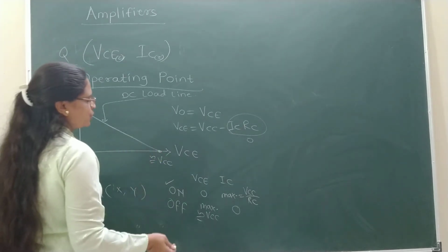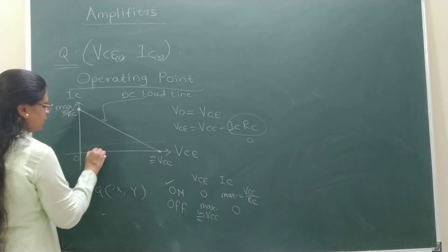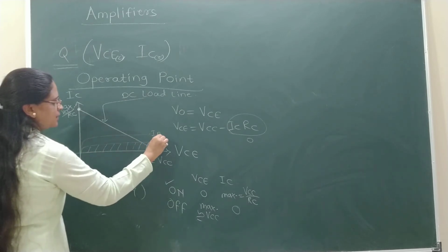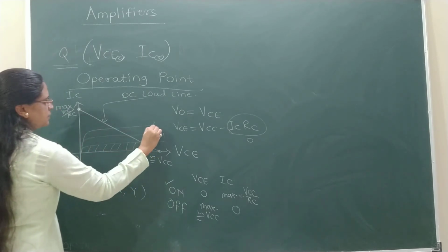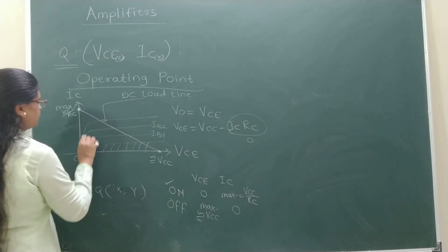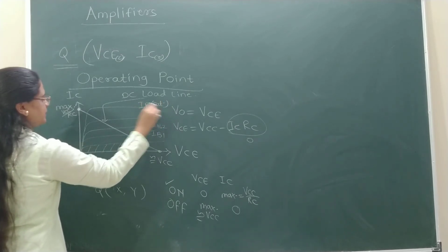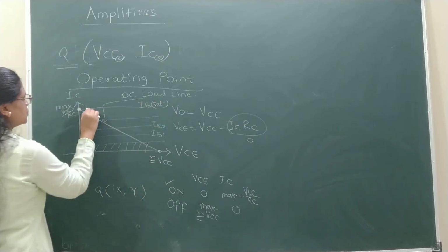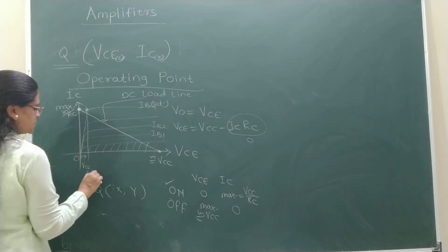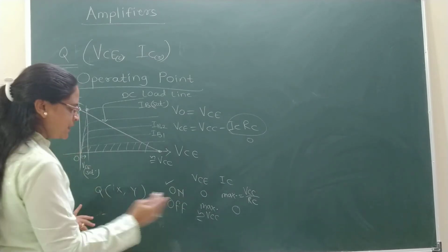But when you apply the input signal, in that case here VBE 0, IB 0. So this shows the cutoff region. As you increase VBE, IB1, increase in VBE, IB2. So in this way we find here IB as saturation, maximum, and at the same time here it shows this much is the VCE saturation. That is, collector current has reached the maximum level and VCE has been reduced.